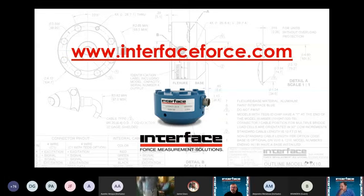Another question: how quickly should a load cell be compressed, in pounds per minute, and how long should one wait after exercising the load cell before checking zero? Bob, I'm not sure I fully follow, but when we exercise our load cells before calibration, it's relatively quick. These are typically done in hydraulic frames, and they're automated to cycle the load and release in, what, Keith? Maybe 30-second cycles. What's the interval roughly on that?